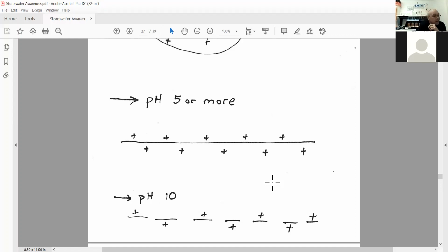Speaking of chitosan, the question here: I've heard chitosan referred to as a coagulant, flocculant, and polymer. Which is it? Chitosan is a cationic organic polyelectrolyte that is a polymer and behaves like a coagulant and a flocculant. So chitosan by itself will start the coagulation process and continue to form larger settleable masses without the addition of a flocculant. A lot of polymers and coagulants out there do not behave that way.